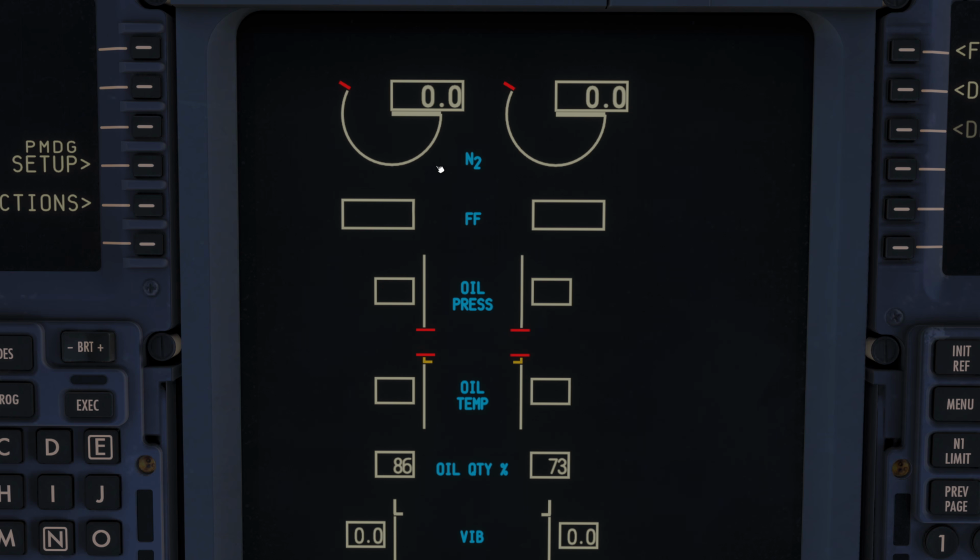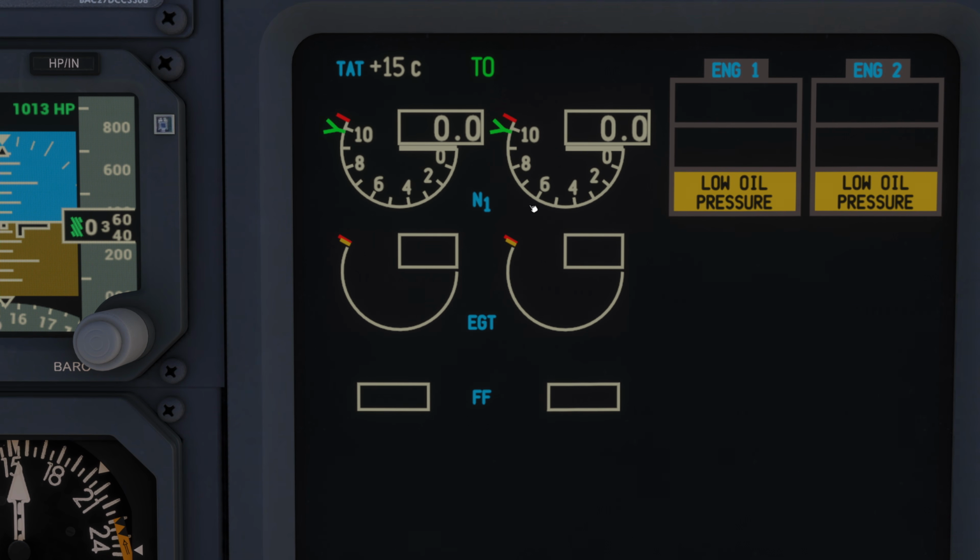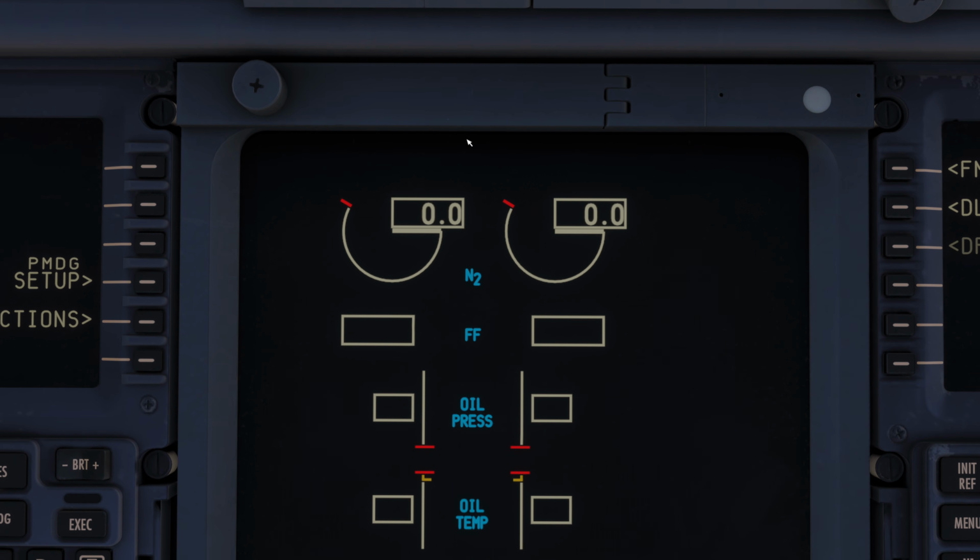So modern jet engines have more than one spool. You usually have what's called the low pressure section, which is where the pressure of the air ingested is still comparably low, which is your N1 indication. And then you got the high pressure section, which is where air has already been compressed quite a bit, is then ingested into the combustion chamber, ignited, and then pushed into the turbines. Now, that part where the air pressure is the highest, that's our N2.